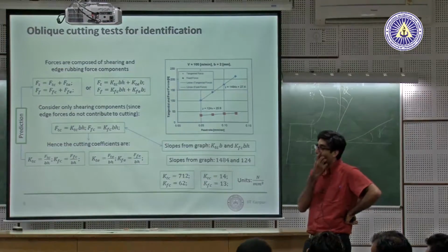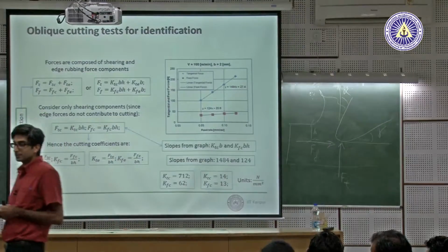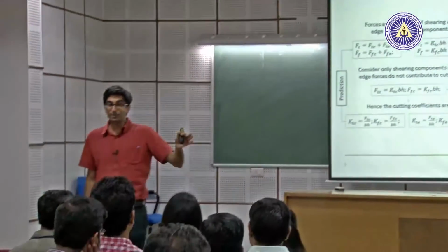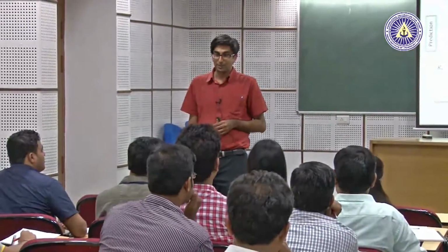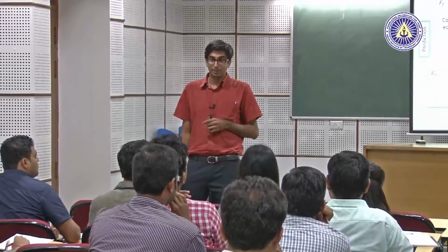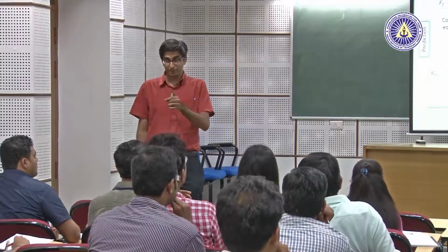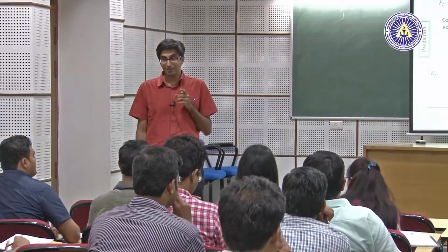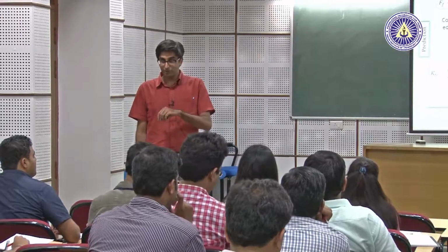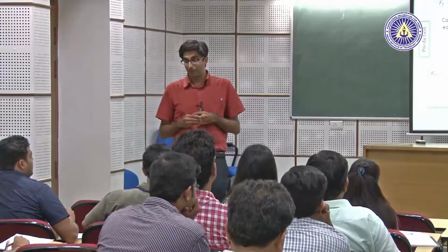Maybe the effect of the spindle speed is already inside taper turning because it's continuously varying anyway. In taper turning, your spindle speed keeps changing because the diameter keeps changing. But your cutting speed V is fixed. Spindle speed is a function of diameter, and that keeps changing.